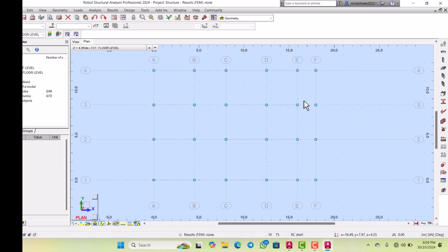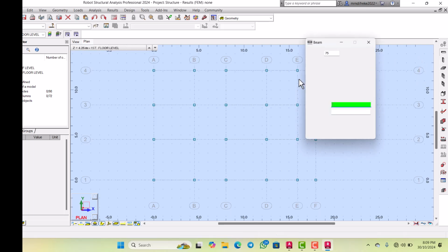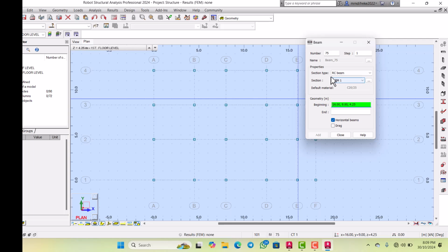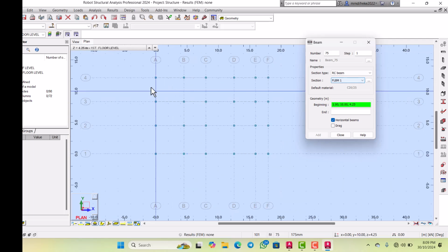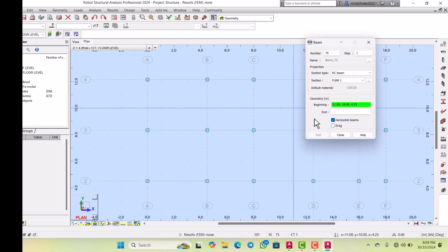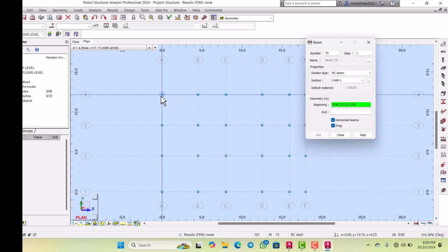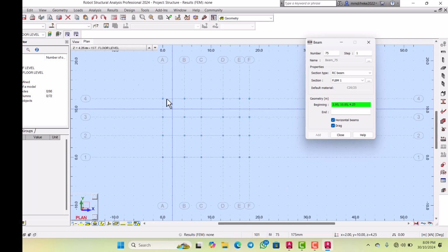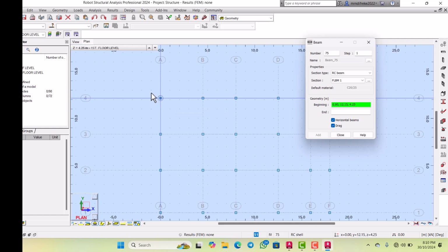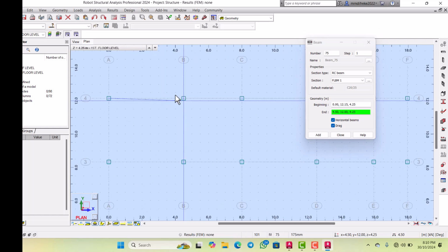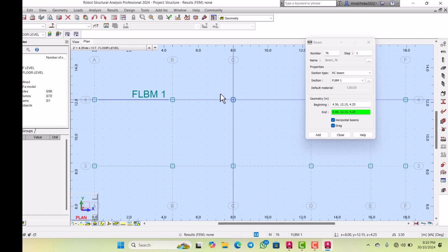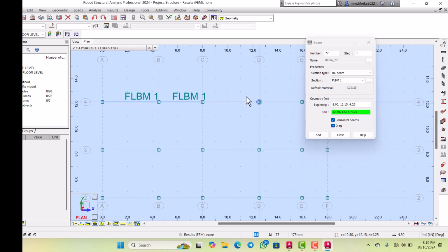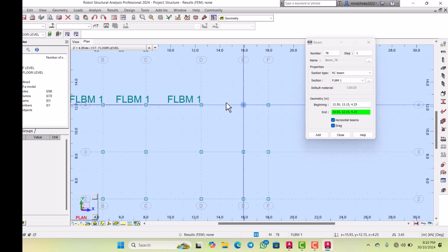Okay, now let's place our beam. The beam that we are going to use is going to be floor beam. You need to define your beam section, because in analysis, for you to be able to run effective analysis and design, you must group some of your structural elements. So you can design them in group. So you see the usefulness of defining this beam section.